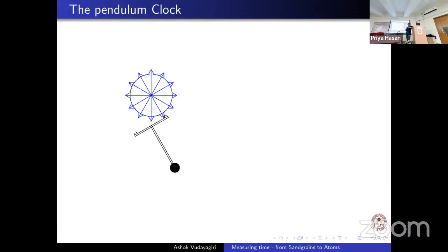So now imagine a pendulum which takes 1 second to go from here to here. That means the wheel can rotate for 1 second, stop. Rotate for 1 second, stop. Okay, so you put a needle and you have your clock. Right? It's a very simple system. And in the jargon, they call this an escape mechanism. Whenever the wheel can escape the pendulum, it rotates.